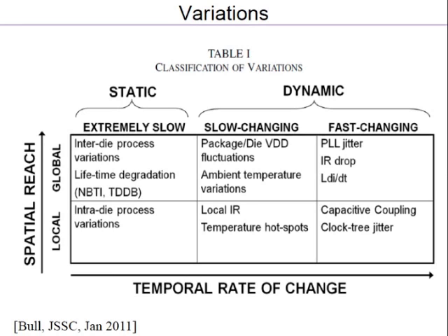But for fast changing, what do you do? You have to margin it. You have to say, look, I'll assume the worst case period degradation and make sure my circuitry will meet that worst case period. That's what is basically done.